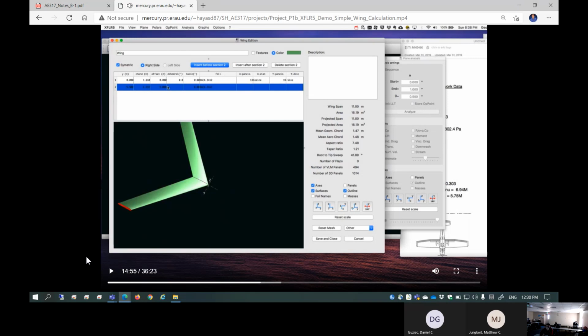This is a wing sweep, of course. You can offset the location of each cross section to put in the wing sweep. This is a linear wing sweep. So it offsets the tip chord way back, and of course it's making it symmetrical, but I just basically set the X value of the leading edge of the tip chord to 5 meters, and you can see it makes it sort of a V-wing thing here. Let me put it back to 0.